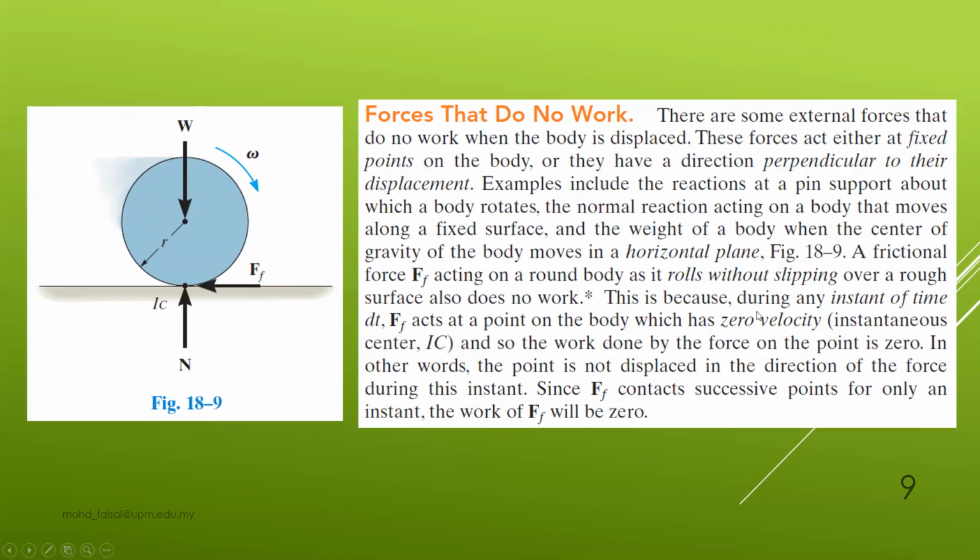It is because during any instant of time, which we denote as dt, the friction force Ff acts at a point on the body which has zero velocity. We are talking about the instantaneous center, IC. And so the work done by the force on the point is zero.